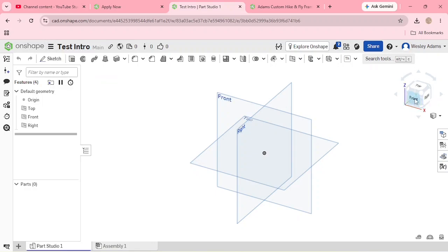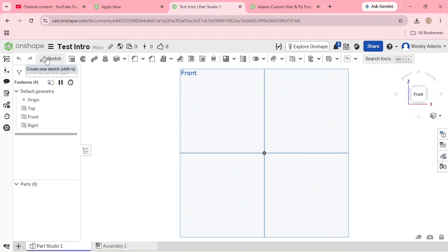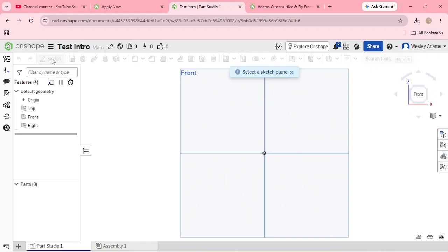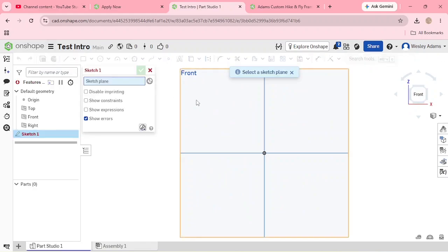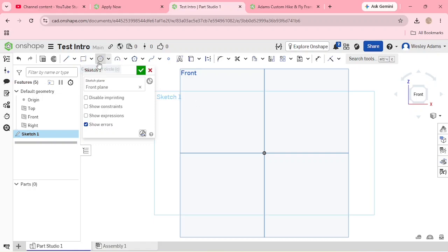I'm just going to show you how to make a part. So when we get to it, you'll see how that part was created. So let's go front. Let's left click here on this sketch, left click front view, left click center point circle, come down here and hover over the center, drag that out, don't worry about the size right now, left click again, hover over the center again, and then left click and then drag that out.